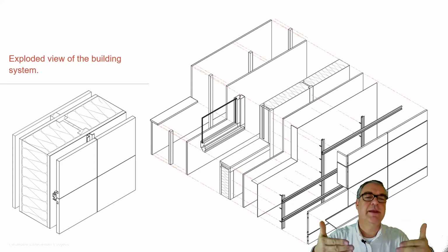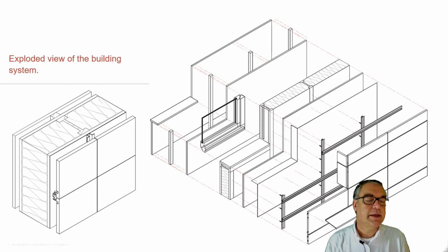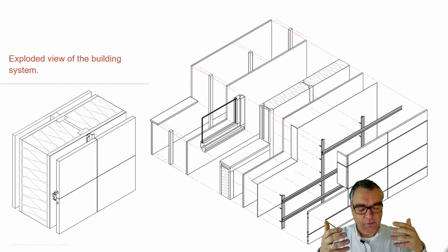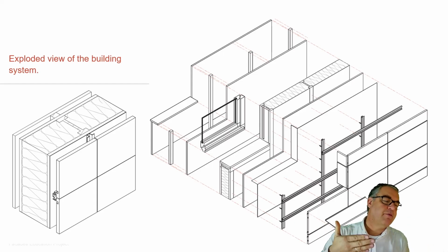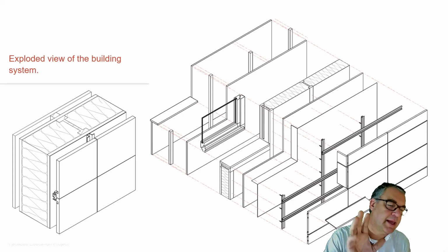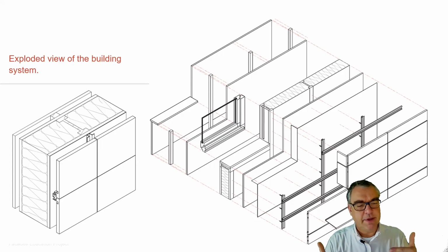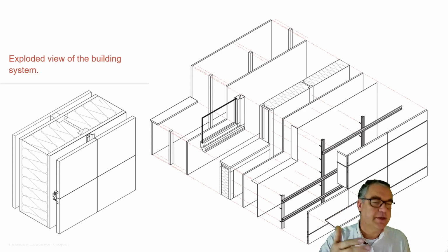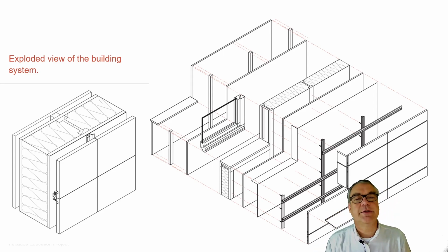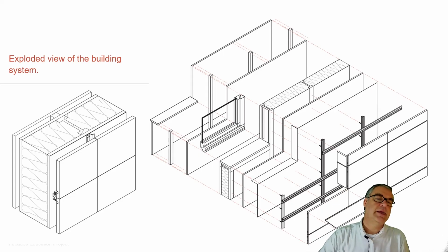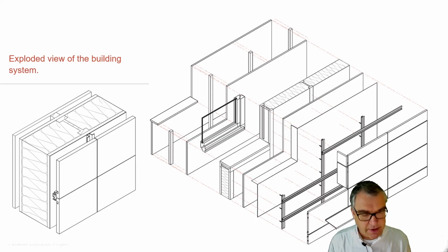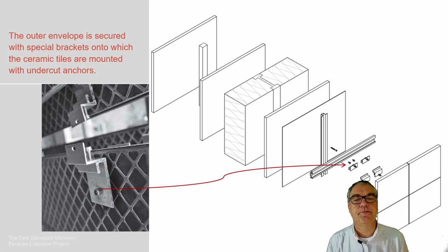And by penetrating the inner layer, if this were the sealed layer, we would create openings which would end up in humidity coming from the inside, penetrating these openings and then getting into the main structure, which we need to prevent. We need to make sure the inner layer is airtight. To do so, we add this additional layer at the inside, being able to install any electricity devices, and then having a separate layer entirely sealed, airtight sealed, to enclose the insulation and main structure, and prevent humidity from finding its way into this system.